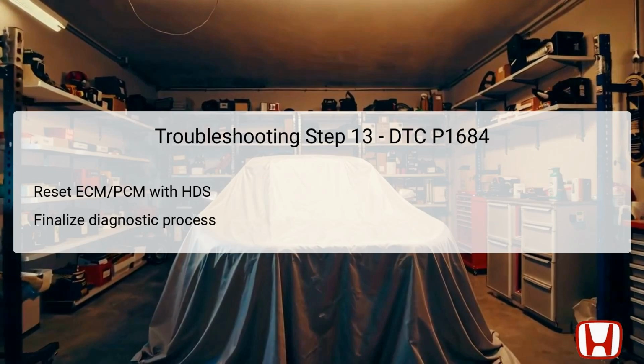The 13th step in troubleshooting DTC P1684 involves resetting the Engine Control Module, ECM, or Powertrain Control Module, PCM, using the Honda Diagnostic System, HDS. This reset is essential for erasing any stored DTCs and confirming that all diagnostic checks are up to date.